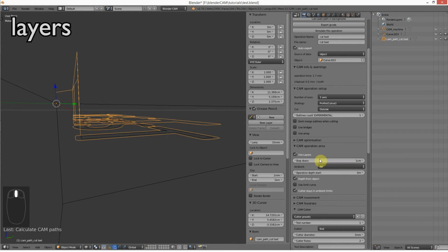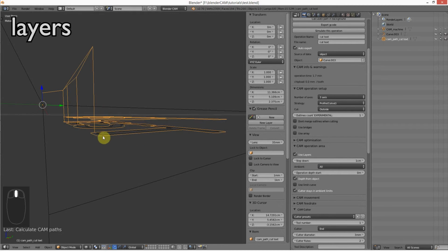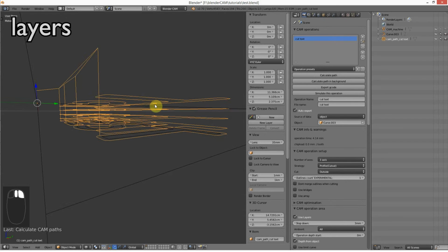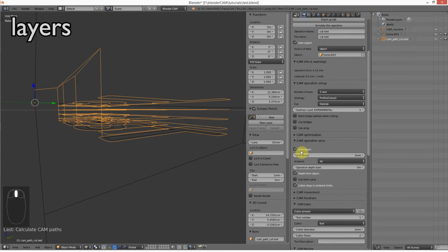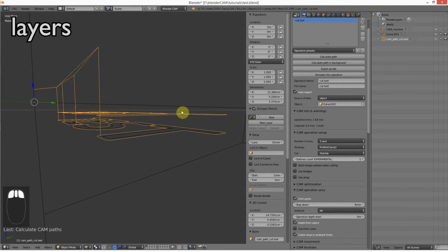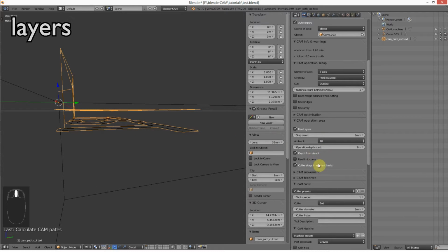The layers are set to 1 centimeter, so it goes 10 millimeters below surface, cuts one layer, then cuts another one. If I make the layers more fine-tuned, let's see, I have now 5 layers. Okay, but I will set it to 8 millimeters because that's my estimate that I will have approximately the same cutting in both passes.